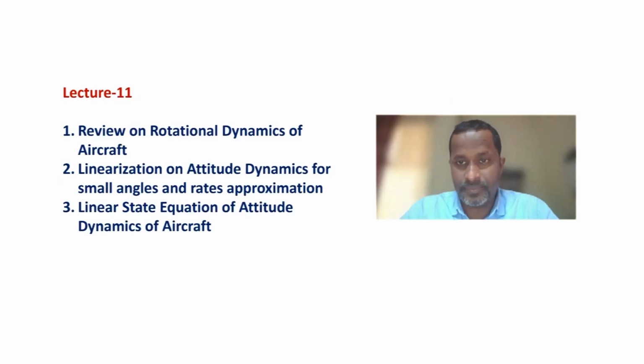In this lecture, we'll be revisiting the nonlinear equation of motion of the aircraft rotational dynamics, or attitude dynamics. Then we'll apply the linearization technique to the system based on the assumption of small angular displacement, and the inertia matrix is assumed to have only the principal moments of inertia.